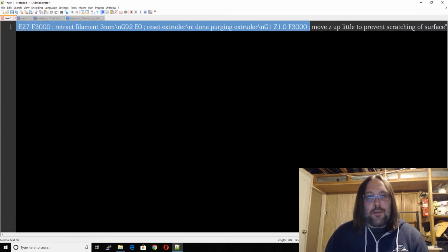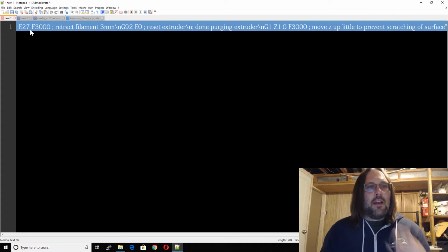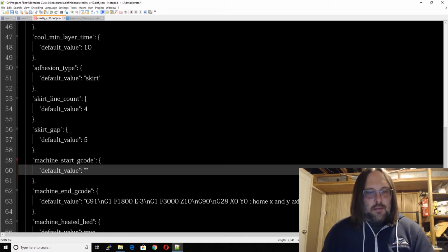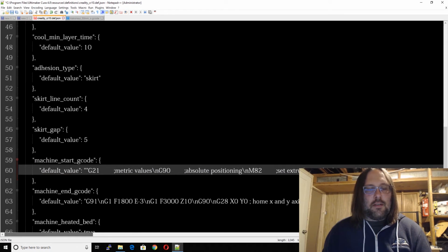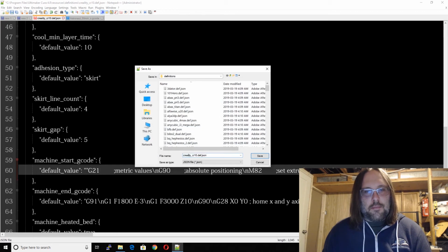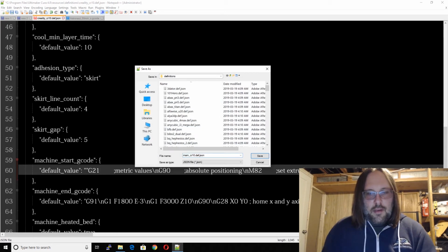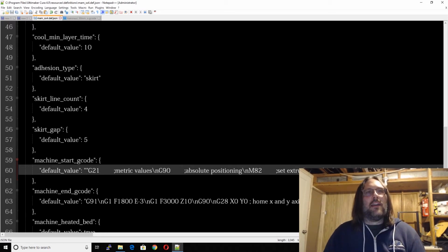So I'll go through all of the G code in a second here, but let's just check out, and we're going to go into our Creality file here, and I'm just going to paste my start G code. The end G code's okay, so we're not going to worry too much about the end G code at this point. I'm going to go file, I'm going to go save as, and it's important to go save as so you don't overwrite the printer that's there. I'm going to go MAM, I'm going to go SX4, and I'm going to click save. So now it's renamed the file to MAM and SX4.